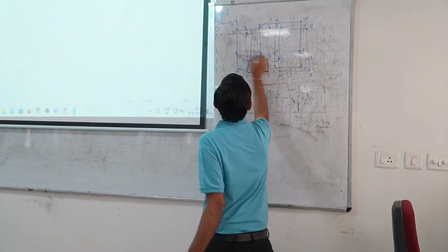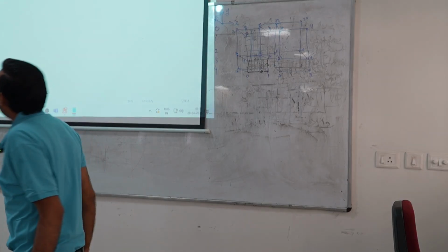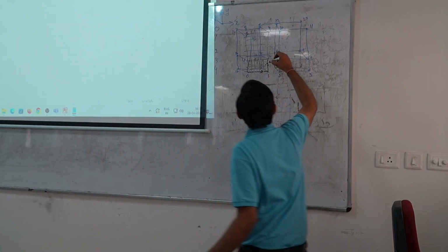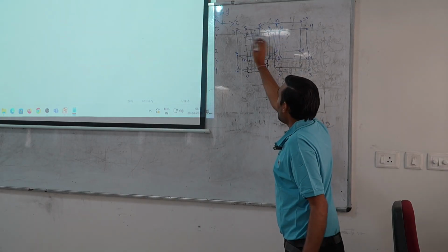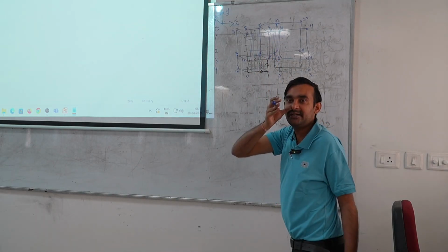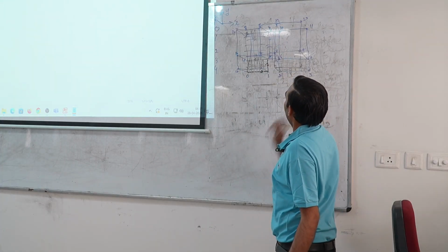So likewise I will be doing 42 grids. After this I am having 4, 42 and 1. So it means in x direction I am using only the 4 divisions for this, but in y direction I need to take 42 only to make consistency. So this will be 42.